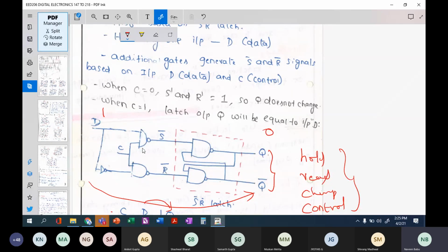So as an engineer, you must be able to control the flow of this particular data. Whereas in the case of a latch here, you are not controlling it. Whenever you give input, immediately this NOT gate will calculate. And if you have a control input also here, immediately this output will be there. And once you have this Q output, you will have an output here too.